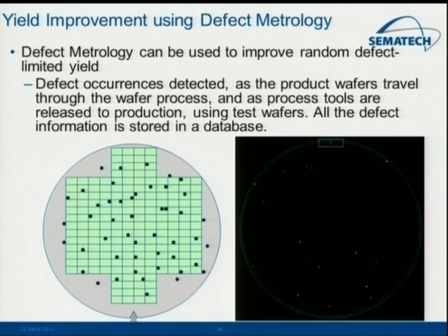So every time you run one of these wafers through a process tool, it would typically pick up a few defects. You want to make sure the tool doesn't become very dirty. If the tool becomes very dirty, you'll quickly end up with zero yield. Because as you can imagine, if this were the example of what the wafer looked like, and you had to go through 50 different device layers, and you put 50 of these stacked up, what's the probability that any of these little individual boxes are going to not have a defect by the end of the process? And the answer is probably 0.